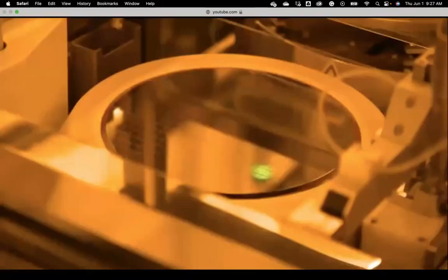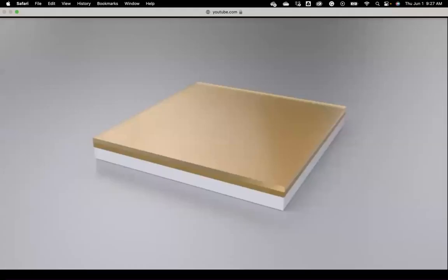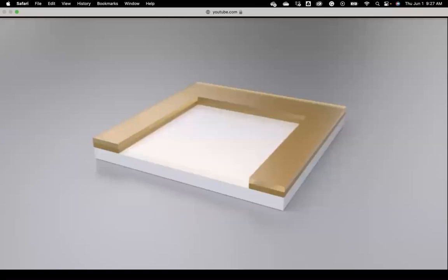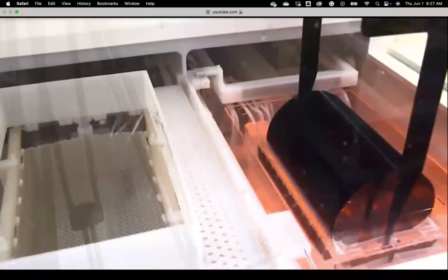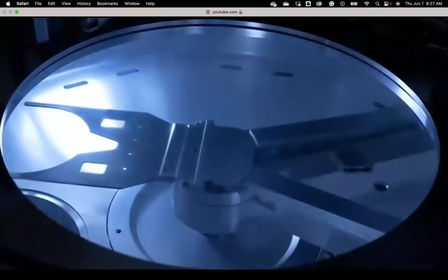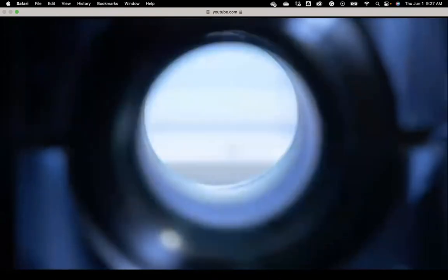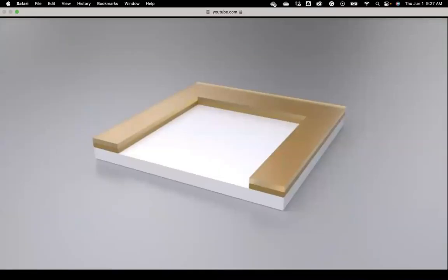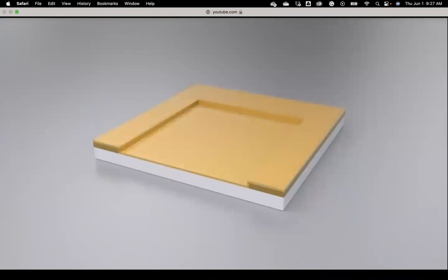After this, the exposed layer of oxide is etched off in the areas that have been developed using wet or plasma etching. With plasma etching, special gases bond with the substrate to be removed in the reaction chamber. This enables microscopic layers to be removed in the windows that were exposed and developed in the previous step. Once the photoresist residue has been stripped and the wafer has been cleaned, the wafer undergoes further oxidation.